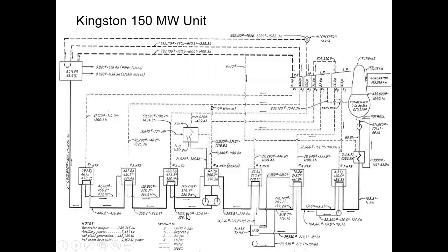I wish it gave me the pressure here. Well, do I get a P over here? It's not telling me the pressure coming out of these pumps, but the boiler pressure is 1,815 PSI. So I would say this is probably 2,300 pounds coming out of those pumps at any rate.